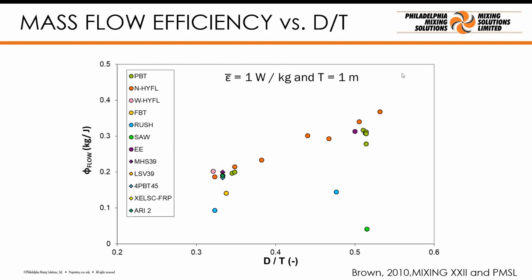And what it tells us is that the most efficient impellers as pumps are the low viscosity, larger diameter hydrofoils, this is the impeller to tank diameter ratio. So as the power number increases, these are the pitch blade turbines, here's the flat blade, here's the Rushton turbine, the efficiency goes down.